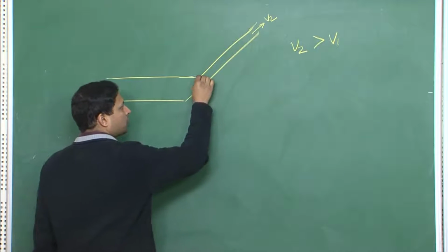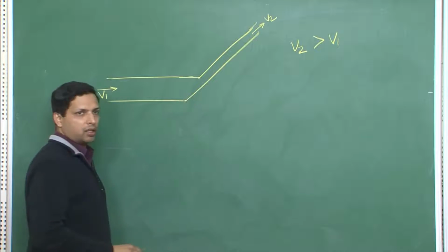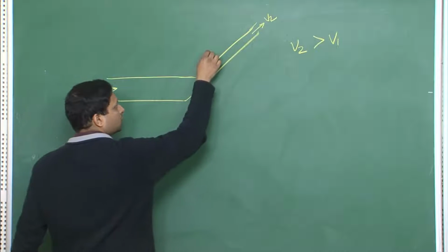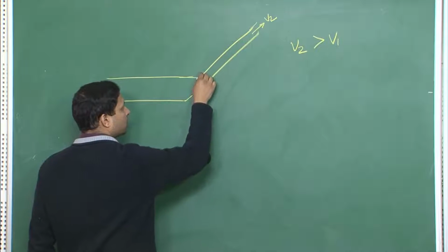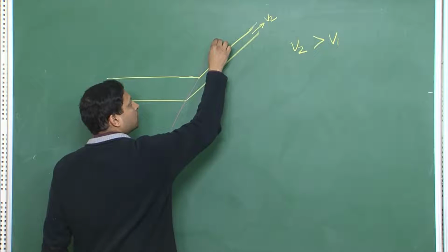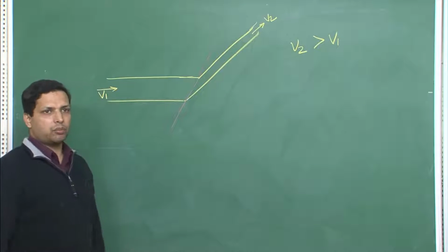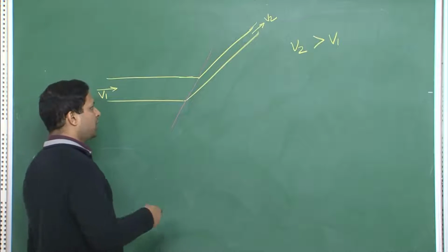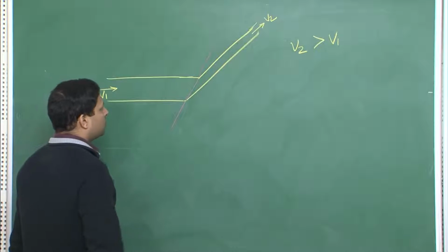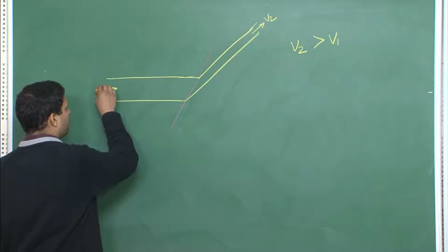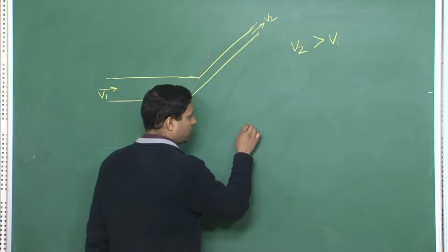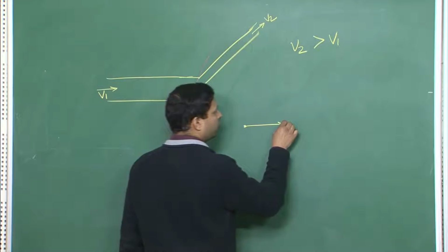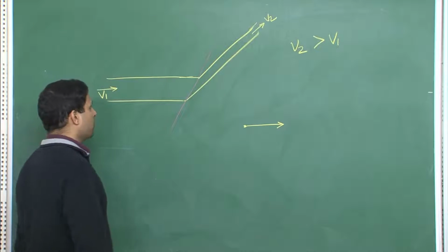Now, through our construction or geometry we have defined a sharp region where this deformation is taking place. This is the plane along which deformation takes place, or where the internal shearing is taking place. Now, to draw the hodograph, we will assume an origin. With respect to that origin, how was the material initially moving? It was moving like this, v1, this is our velocity v1.